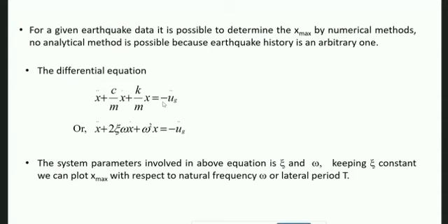It can only be described numerically. That means the time versus acceleration at a regular interval of time, say 0.02 second, which is normally taken as the interval in all the accelerographs. So at an interval of 0.02 second, what is the value of the acceleration?